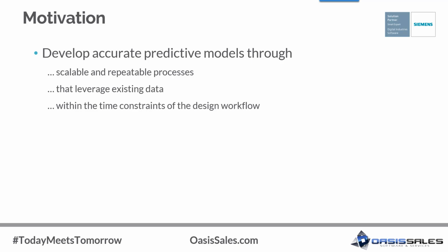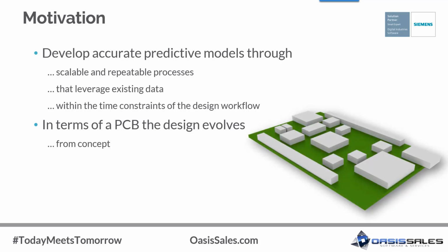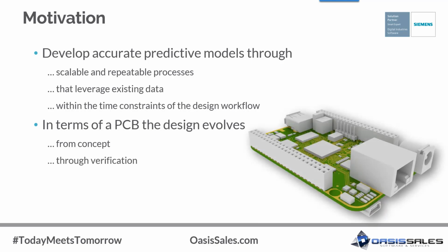Within the time constraints of the workflow, again, for thermal analysis of PCBs and of electronics in general, analysis provides the most benefit if it can provide insight during each phase of the design flow. For PCBs, the design evolves from concept, where PCBs are modeled using more assumptions to uncover any useful trends or determine feasibility of a design, through verification, where the final thermal analysis and design are performed prior to prototyping and testing.